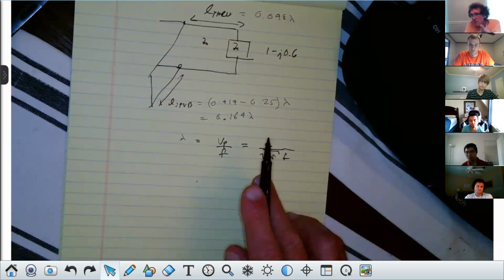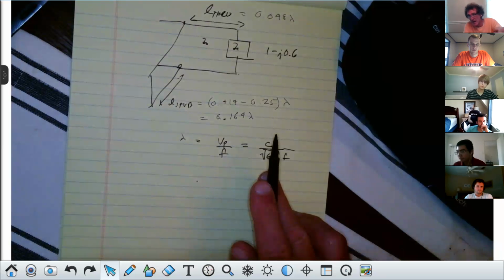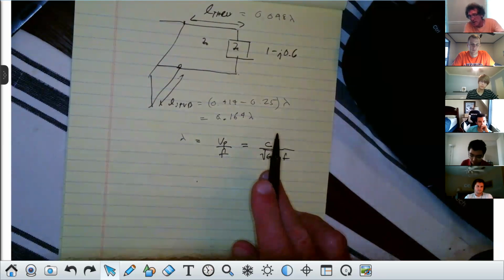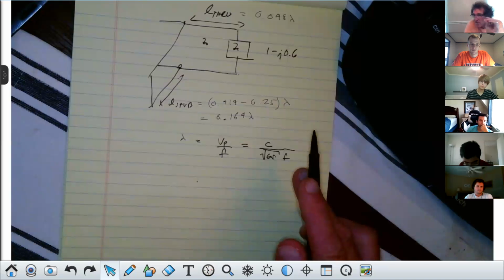All right, what you're going to be exposed to is a lot of different boards that are used to delineate or pattern things that will be transmission lines and stuff like this that they'll mount literal chips on. Now, I can't show that to you right now, but I will later, hopefully. But remember this one thing when you're doing a design. The people that delineate these things do not want things in lambda. They want it in meters, centimeters, or millimeters. And usually they hate inches. They want it specified in the MKS system or System International.